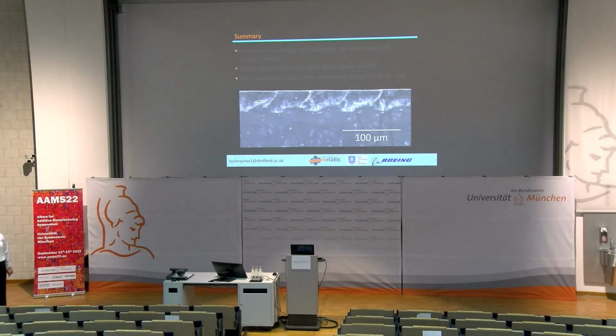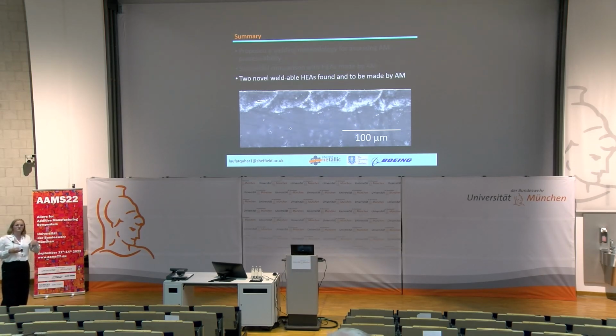So just to summarise, I proposed a welding methodology for assessing AM processability, and we compared it with the HEAs which were previously manufactured by AM, and we've seen a remarkable similarity. And we found 2 novel weldable HEAs, and these are now going on to be manufactured by AM, both through pre-alloy powder and elemental powder in situ alloying.